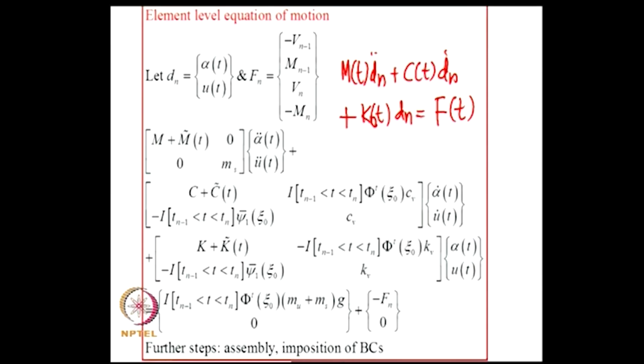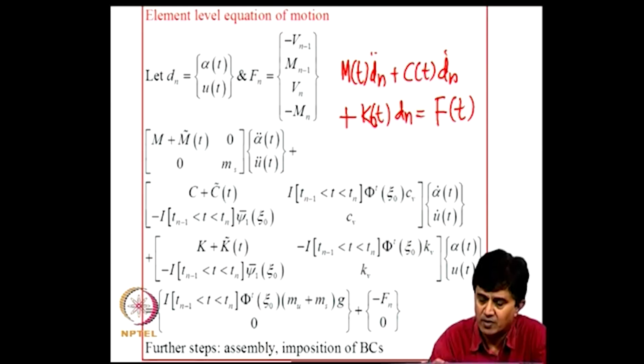Now, what is to be noted here is that because of the time dependency of the structural matrices, these equations although they are linear, the concept of natural coordinates etc. are not applicable here. So, you can't talk about natural frequency and mode shapes for this type of systems, and the only way to tackle these problems quantitatively is to integrate them using one of the integration schemes that we discussed, like the Newmark beta method or any other method that we discussed earlier.